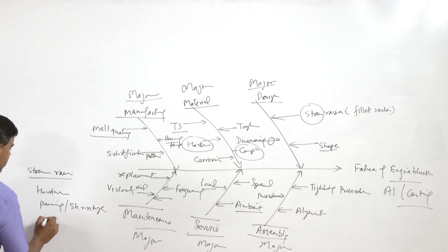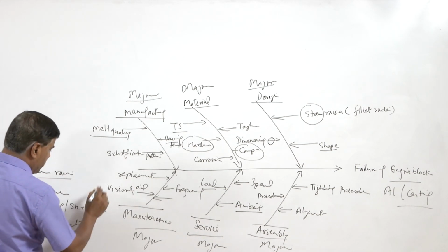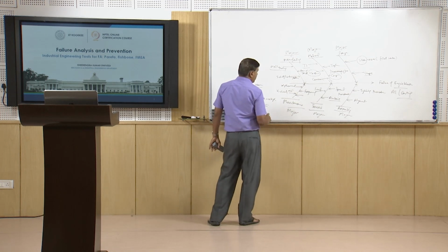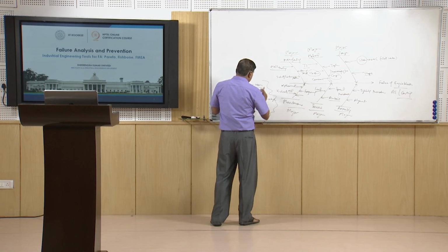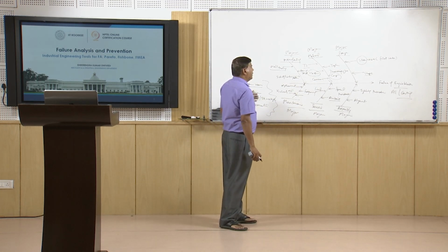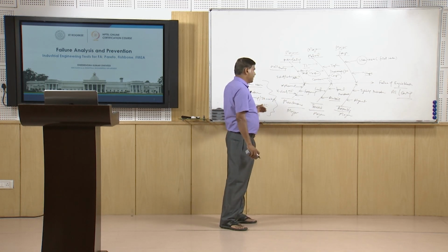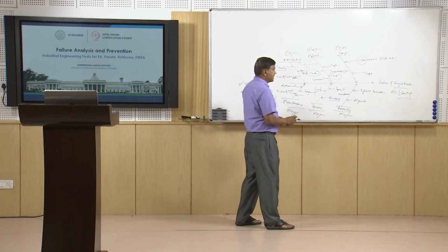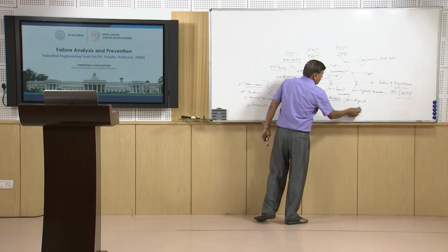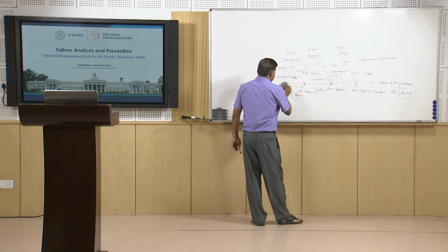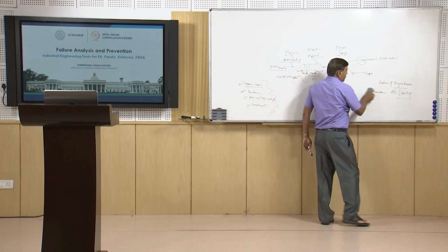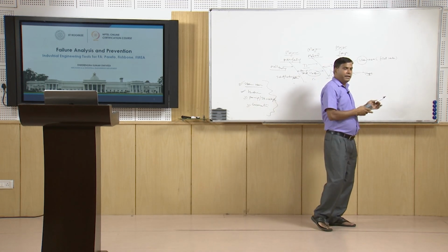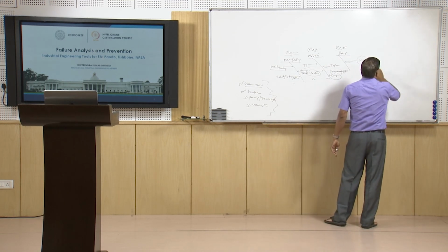And then improper maintenance, maybe the kind of lubrication can be one of the important ones. So, a few big or significant minor causes are identified which will be actionable, and then investigation is carried out with regard to these, whether really the engine blocks which are failing are failing due to which of the aspects, so that the proper corrective action can be taken in order to avoid the failure of the component in subsequent stages. So, this is how actually the fishbone diagram or the Ishikawa diagram can be used to prepare a detailed list of the various major and minor causes to a particular effect which we either want to avoid, or we want to encourage or incorporate, or we want to have.